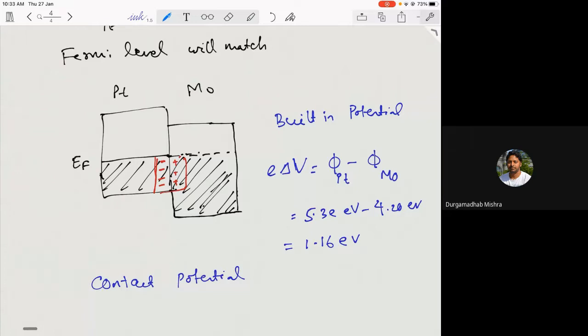That's why you will see a jump in the vacuum level at the junction, which normally you don't actually see, because it is just the energy where the electron will be free. So there will be a step in the vacuum level of both, so that they keep their work function exactly the same.